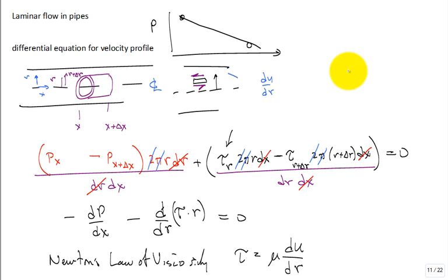Maybe to make it more familiar, you flip it like this, and here's the center line, and here is r. R starts at 0 and goes out to cap R. True? Kind of take it in your mind and flip it. Then the velocity profile I'll plot going up for u, and it'll be like this. So the slope of this line is negative.